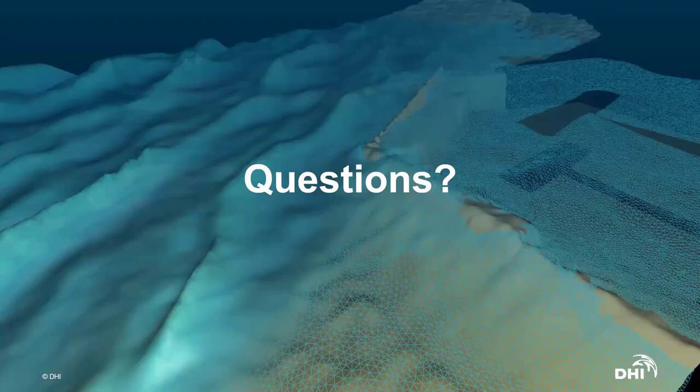Is the model capable to simulate breakwater covered by a sand layer? Yes, it is capable to model that, but again, it depends on the approximation of the sand layer with the porosity zone. So you could imagine that you had one porosity layer on the breakwater which had one porosity setting, and then you had another porosity layer beneath that where you had a different porosity setting. In that case, then yes, you can simulate breakwaters covered by sand, for instance.